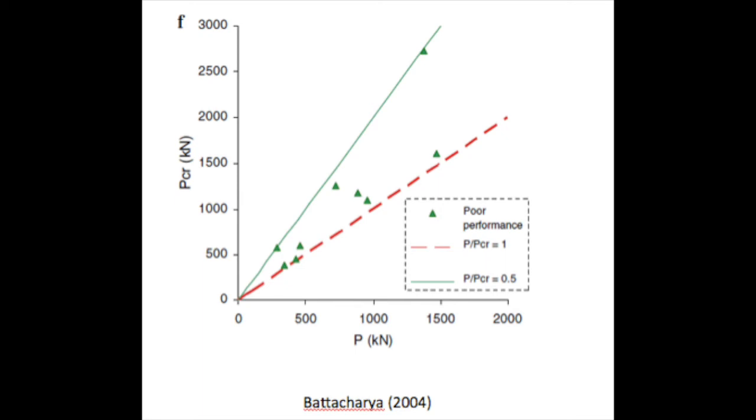The steps to calculate the critical load, which is the maximum load the pile could carry due to buckling, can be found in my paper. However, the critical load and the actual load for piles in past earthquakes that were deemed long, slender columns were analyzed and compared. If you look at the graph, poor performance occurred when the ratio of actual load to critical load was greater than 1, which means that the critical load for buckling was less than the actual load that occurred. This proves that buckling needs to be accounted for when designing piles for liquefaction.